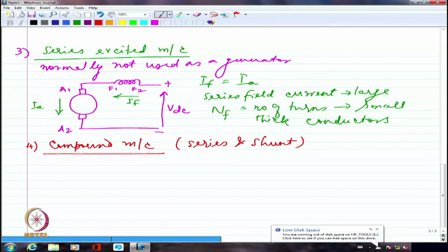So the torque developed is going to depend upon the demand from the load side in the case of a motor. If the mechanical load demand increases, I'm going to have more and more current. If I have a generator, depending upon what kind of resistance or load I have connected, I'm going to have more or less demand of current from the machine.